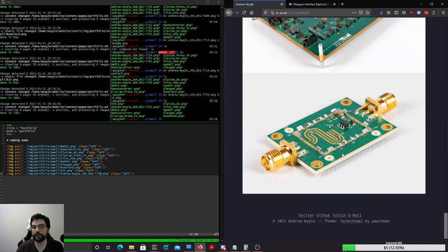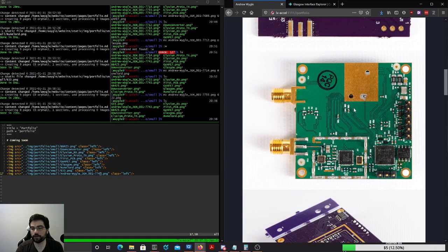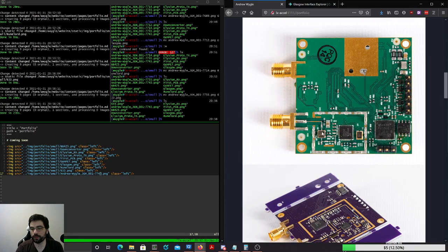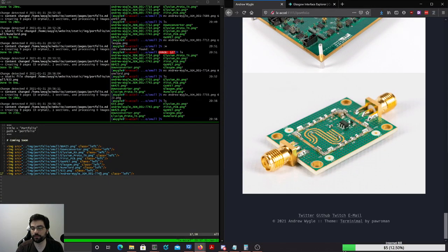Right, so the Elysium had a very low power consumption, which was great, but it came at the expense of noise figure a little bit because the receiver IC was highly integrated. That means there's not a lot of room for a nice isolated low noise amplifier. So we had this off-board LNA, powered by a bias T that was a load option on the Elysium. This inductor here injects DC power, and then it goes in here and powers the amplifier.